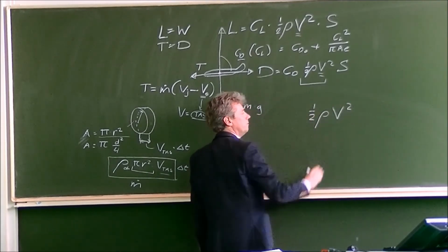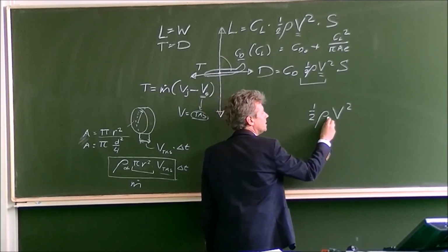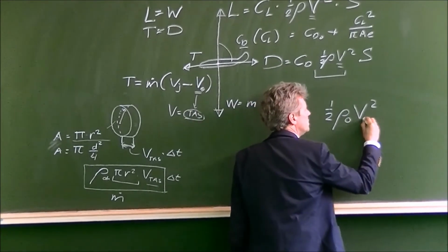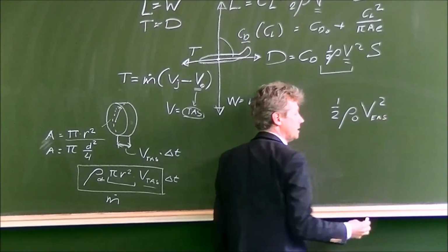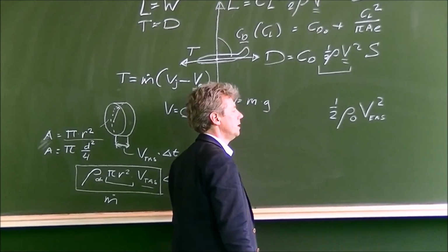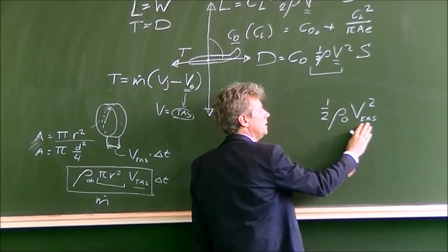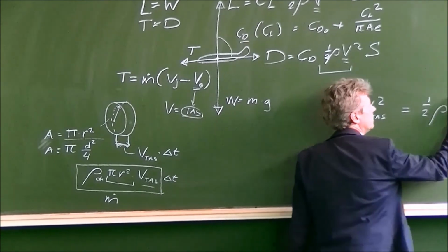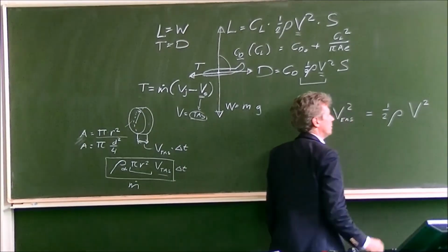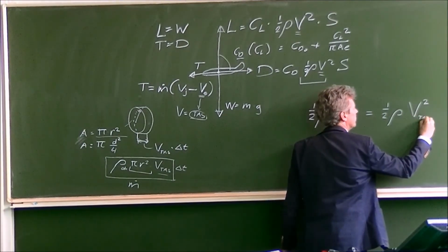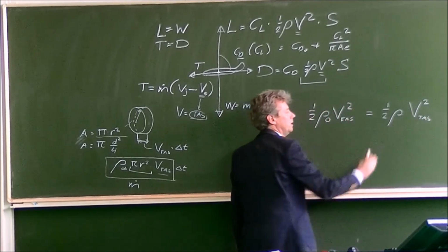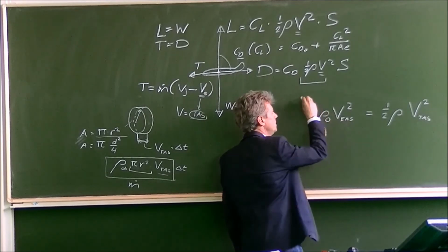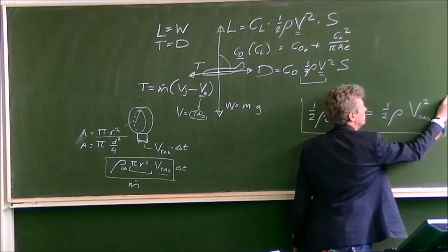From having the half rho v squared, we can calculate the v, but this is calibrated at sea level, so for the rho 0, and we call this the equivalent airspeed, but at sea level it's the same as the true airspeed. But later on the total dynamic pressure is given by half rho v squared, and this is then the true airspeed. Both the speed and the density vary, but to keep it simple, we assume that just the speed changes, which means that this is always true.